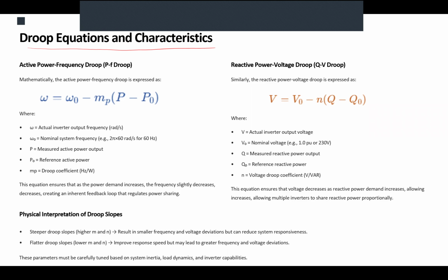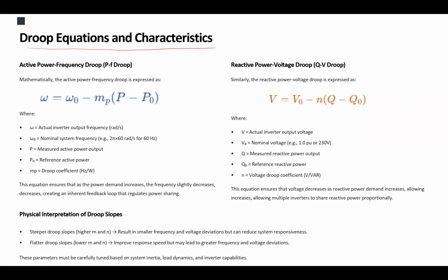One would act on frequency, another one would act on voltage, because grid forming wants to dictate, mandate, stabilize, whatever you want to call it, the frequency and the amplitude of the voltage at its output. They want to shape a stable grid, which means a stable frequency and a stable level of voltage. So we have two basic functions in our control system.